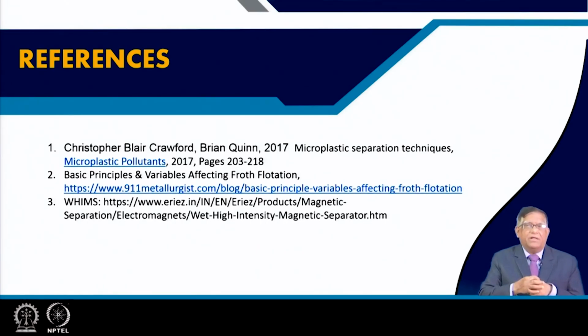If it is centrifugal separation, how much centrifugal force is coming up, and in that force what type of particles can it pick up? Is the flow continuous or intermittent? What is the relationship between your evacuation and your feed? Try to find out those variables, and when you make the relationship between different variables, then we say that we have developed a model.